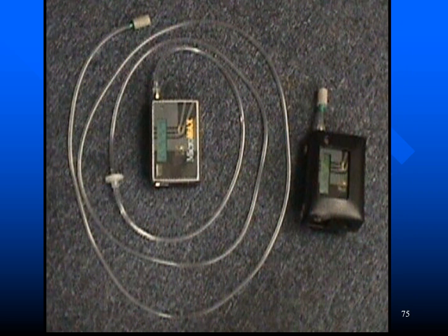Now you'll notice in this type of monitor it has a long tubing. This allows the person that's monitoring the gases to slip that long tubing down into the confined space without having a human being enter the space, so they can check for toxic levels of gases before they enter the space.